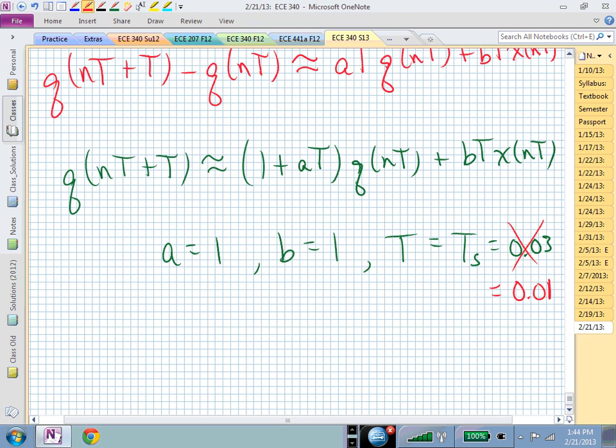So this now might be there. And now you have a way to iteratively compute your solution. All you need to do is sample your x, and we were given x of t, and now you were given the initial condition on your voltage for your capacitor, and now you can simply iteratively generate the solution with this numerical approximation.